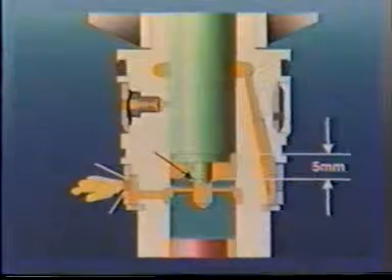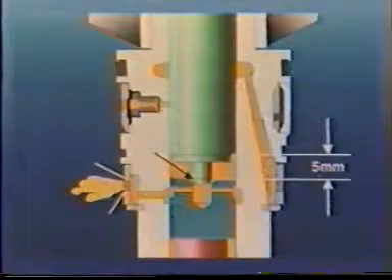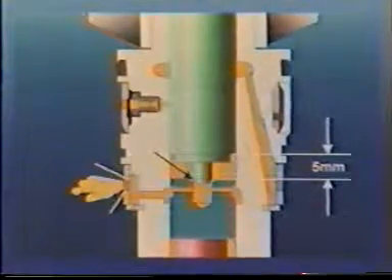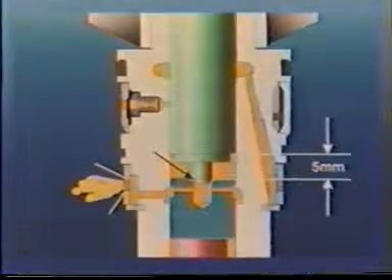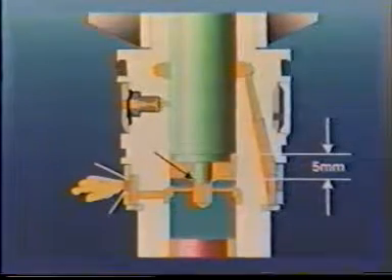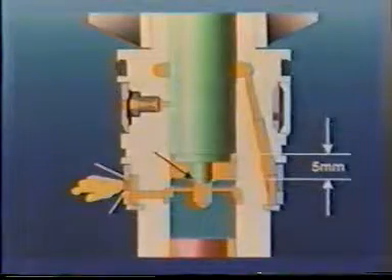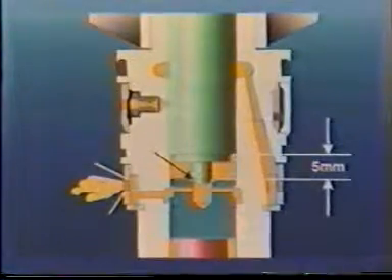During the last 5 millimeters of upper plunger travel, the nose on the bottom of the upper plunger engages with the port in the timing plunger. The clearance between the two ports acts as an additional flow restriction on the fuel in the port. This additional restriction keeps pressure on the lower plunger while the rest of the timing fuel is spilling. This feature is needed to ensure that the lower plunger does not unseat during the transition from the ramp to the nose of the camshaft lobe.